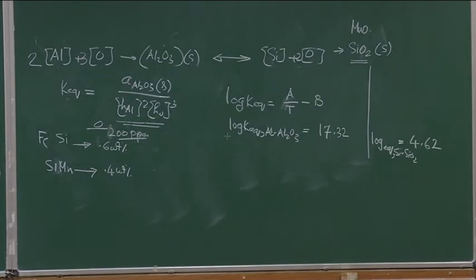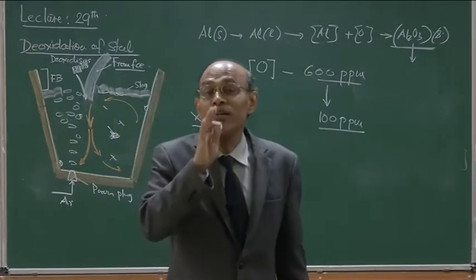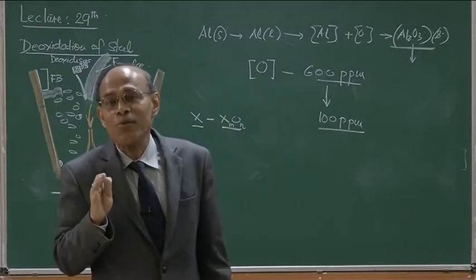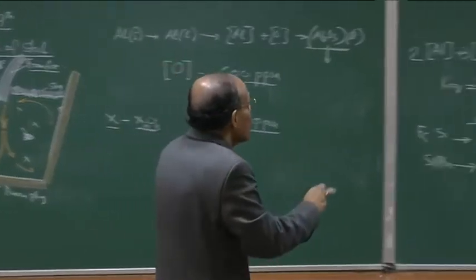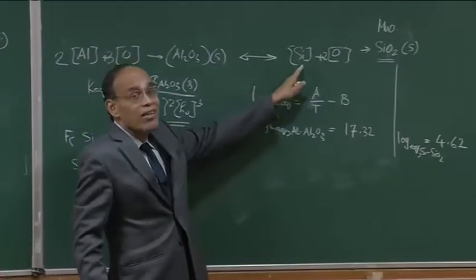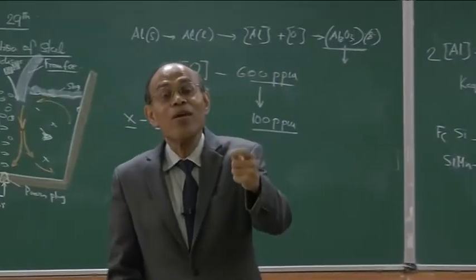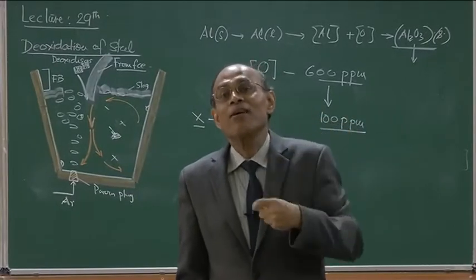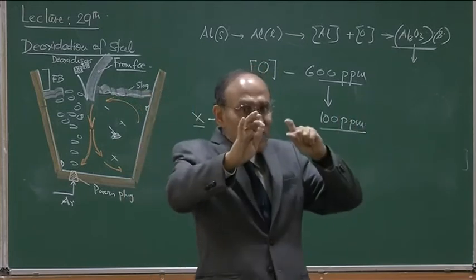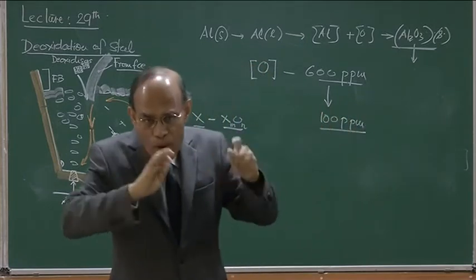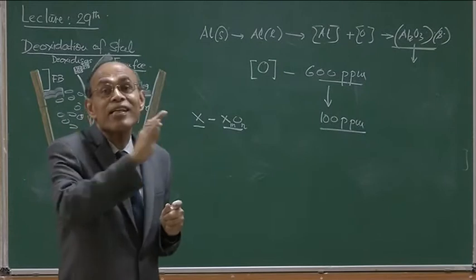So, even though we have eliminated all of the silicon during the primary steel making process, because of deoxidation, because of residual silicon content coming from the deoxidizer elements, we can see that the final steel will contain some amount of silicon. Of course, that level of silicon has to be within the maximum value specified by my customer. So, I will use all deoxidation elements in such proportions that the prescribed target composition is not violated at all.